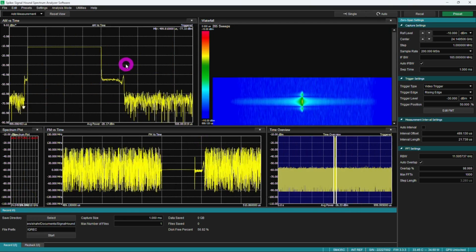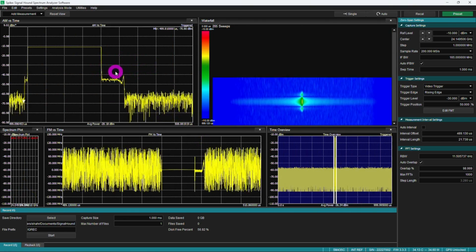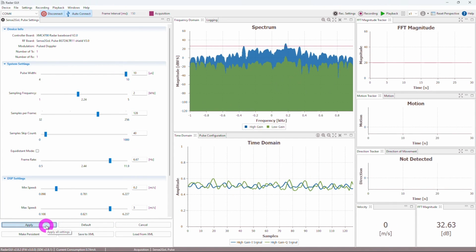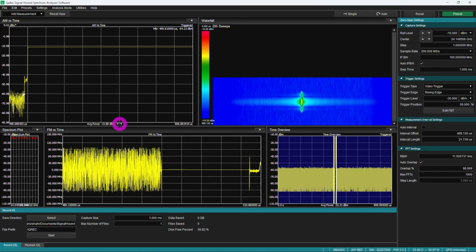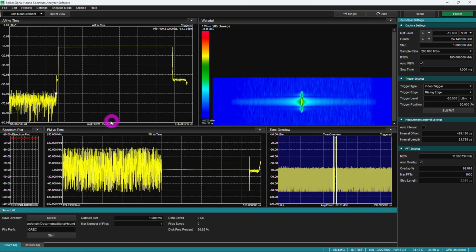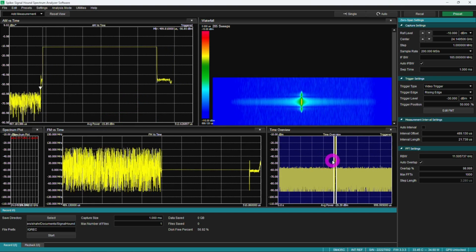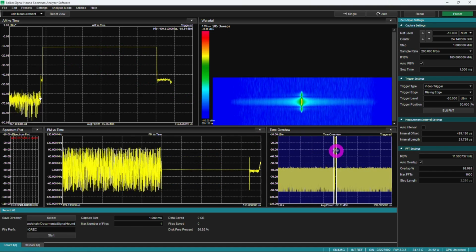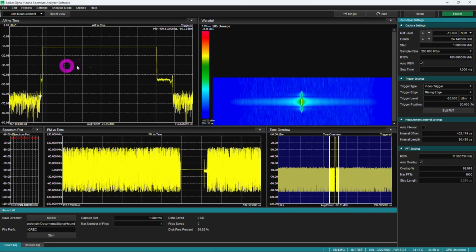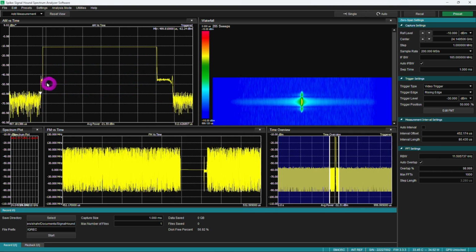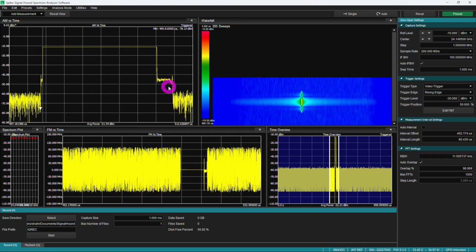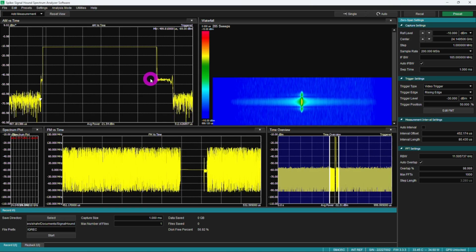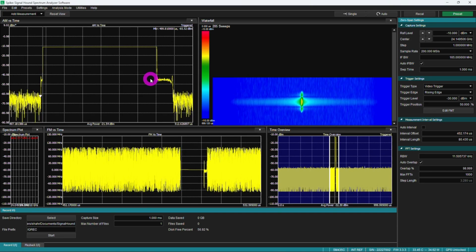We can also quickly verify that the pulse is indeed adjustable from the radar GUI. We go over here. Let's turn the pulse from 4 microseconds to 10 microseconds. Press apply here. If you go back, you can see that the pulse is indeed quite a bit longer. So this is exactly what we would expect to see from this. We can move that a little bit to center it around the pulse, and we can see the complete pulse. We can look at the slightly longer window. It looks good. So the radar is doing exactly what we were expecting. Now the arming and the disarming part of the radar doesn't change no matter how long the pulse is, because that's independent. That has to do with turning on and off the internal blocks, which is again consistent with what we would expect from the chip.